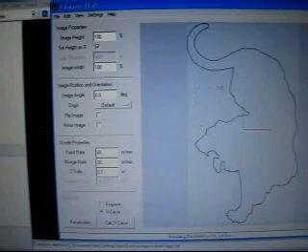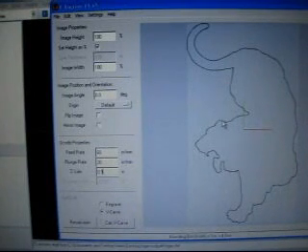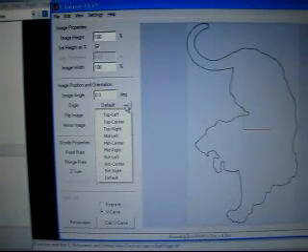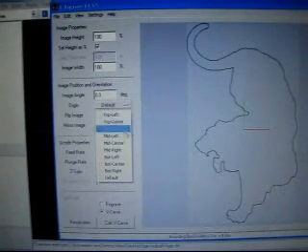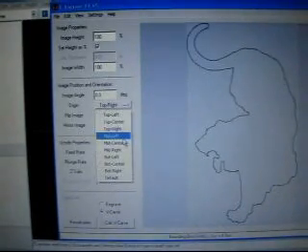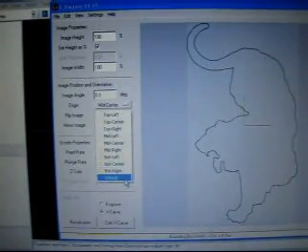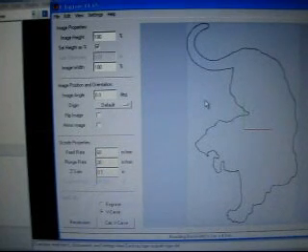If you come into this program and have designed something in an outside program, such as CamBam, which we just did, and changed the point of origin, you want to set this to default so you know where you've changed it to. Otherwise, you could just set it to wherever you want. In this case it's going to be mid-center anyway, but we've changed it, so I can go ahead and put that on default.